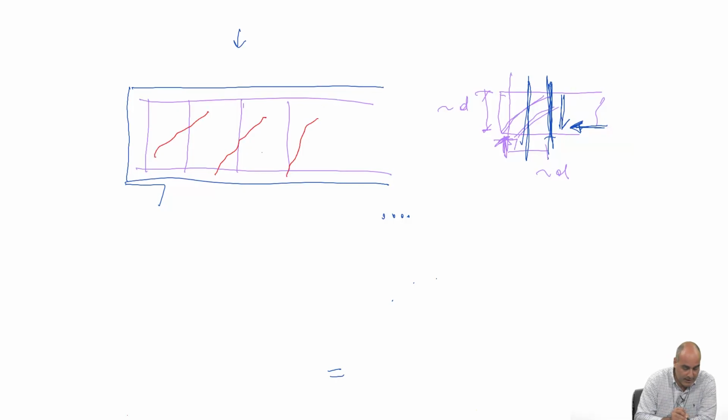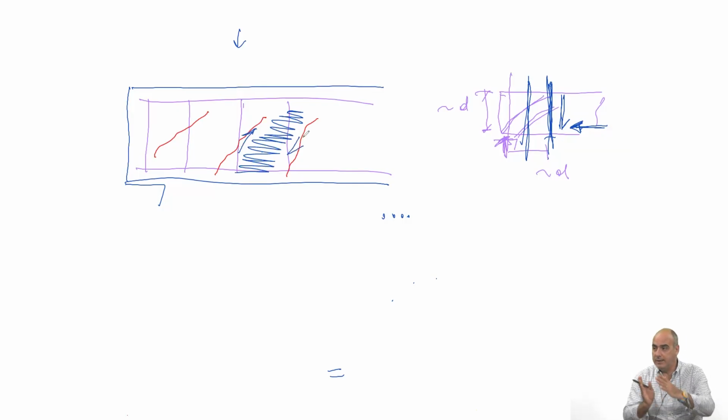So your strut is something in between the cracks, which is experiencing these aggregate interlock forces, but which is also experiencing stresses transmitted by the stirrups, which are tensile.